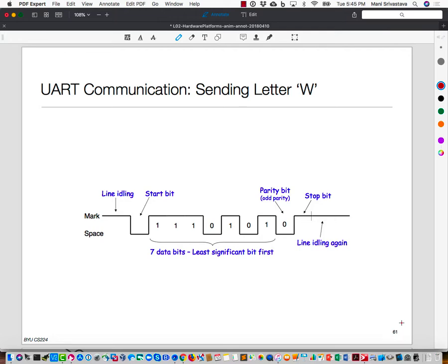And remember, these are two separate systems. They don't have a common clock, right? So the receiver, from this signal, has to figure out how to sample. First, we can tell the transmitter and the receiver what the baud rates are, and they can set the baud rates according to their local clocks. If we assume the clocks are reasonably accurate, we are done. For UARTs that typically works fine, which is why in CoolTerm we had the baud rate of 9600 baud. That tells it what rate to sample. It still has to figure out when to sample, and it does that by looking at the edge.